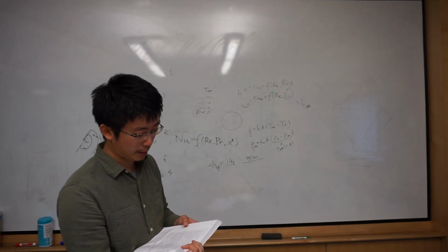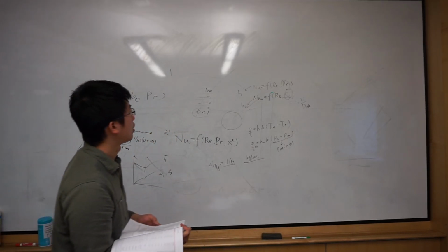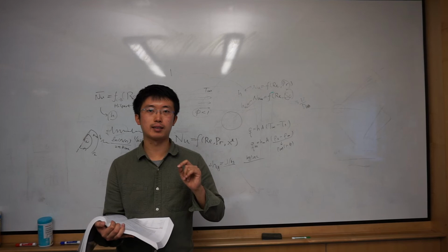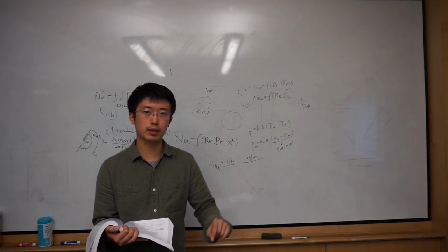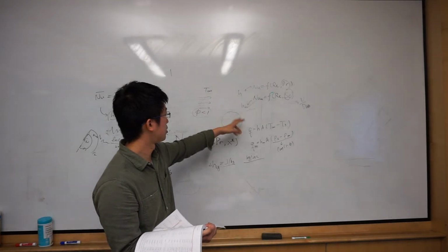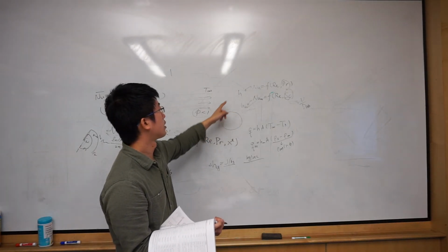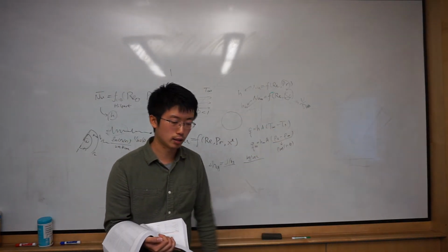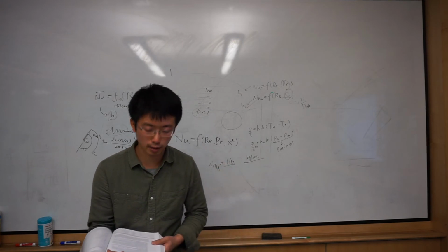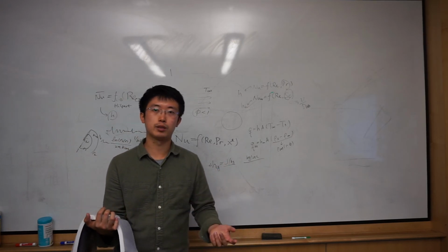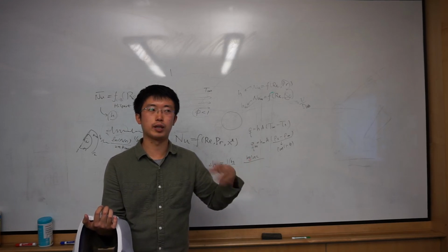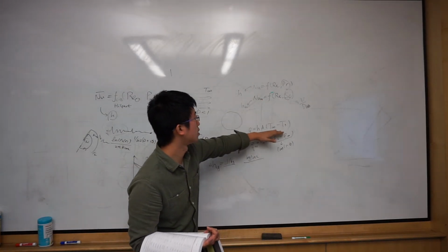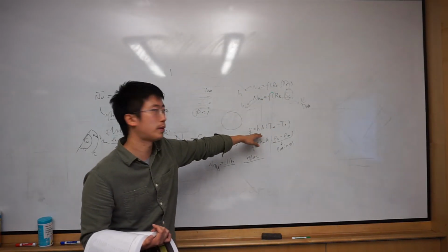And what is an empirical heat and mass transfer coefficient? Basically, only for the laminar case do we have the exact solution. In other cases, for other shapes, especially when you transition to turbulent, we don't know. The other is boundary layer separation, which is another problem. So we just do a lot of experiments and put all the results together. This equation is by definition.